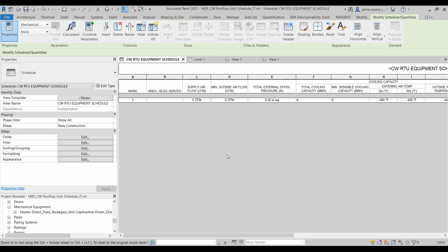So whether that is out of the box content, whether that's manufacturer content, both of those contents either come with family parameters or their own custom shared parameters, but they're not going to work in your standard schedule most of the time. So we're going to have to go through and swap out those parameters and then add those additional parameters to get that to work with your content.